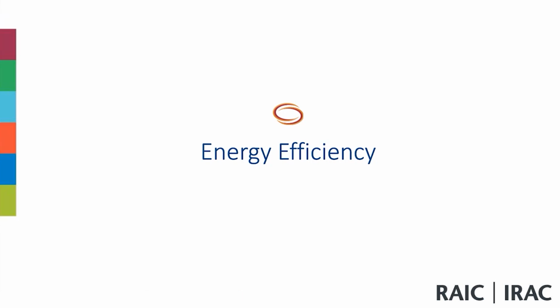Okay, SR is associated with the 1 in 50 rain load in kPa, and SS is the 1 in 50 ground snow load in kPa determined in accordance with subsection 1.1.3. So the 1 in 50 ground snow load and the 1 in 50 rain load are the SS and SR that are provided for you under the tables in climatic, right?